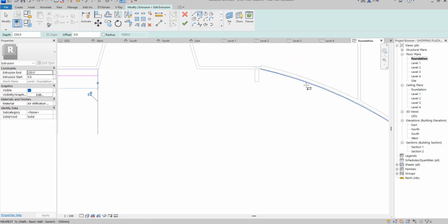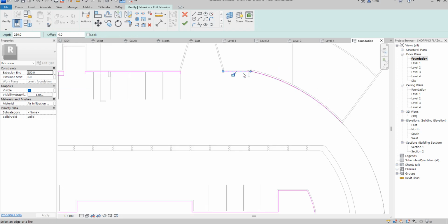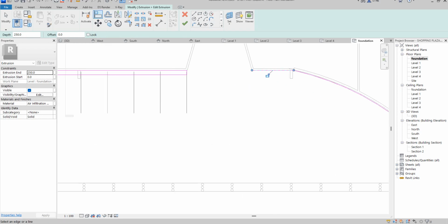So this is it. So now we go ahead, create this one. Okay, then offset again. You can offset this. What is the distance? So you check the distance. Let's say 500. I didn't do measurement towards that one, so let's say 530.